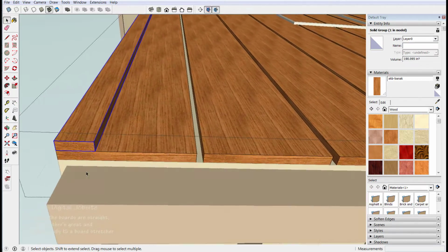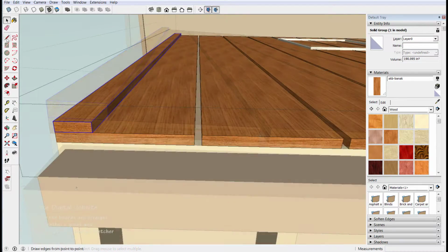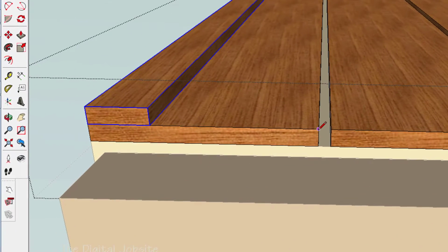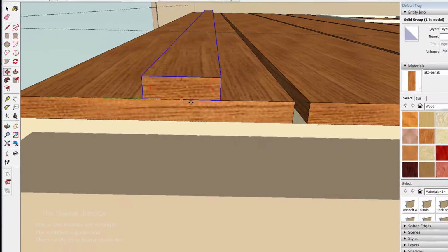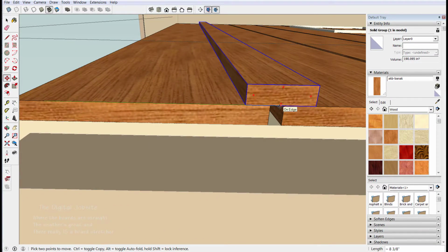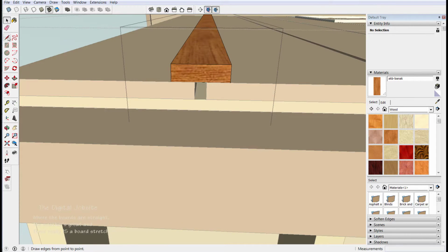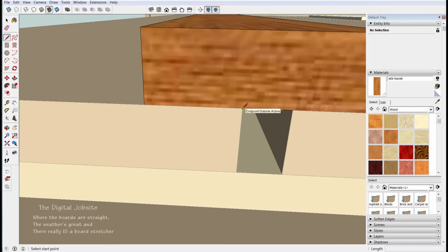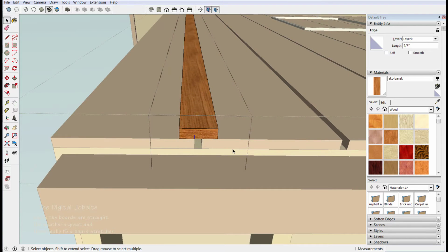So we've got one batten put in place here, and I want to center the battens up over the grooves in the siding. So I'm just going to draw a line in between 2 pieces of siding, like that. I'm going to take this batten and move it by grabbing the center point and moving it to the center point of this little line. And on the bottom of the board, I'm just going to put a little tick mark from this corner out. Let's just go 0.25, 1/4 inch line. Go outside the board group.